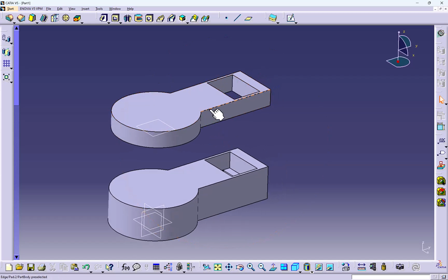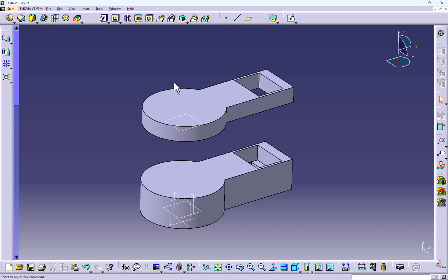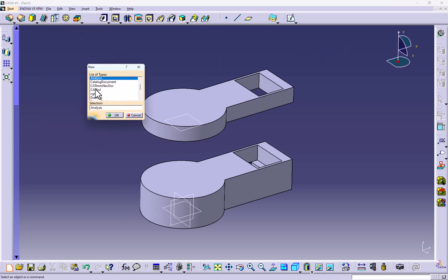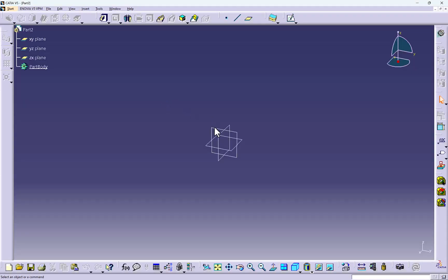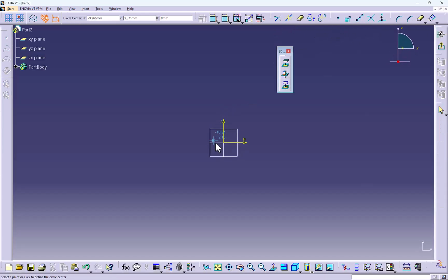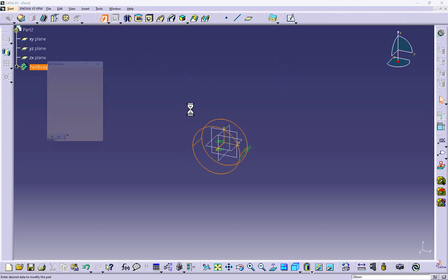Next, we can do one thing here. We have circular body cases. Now this is for the normal case we have seen. We'll see how to use projection for circular body cases. Let me take a new part file here. We'll create a circular object. Let's create a simple object to be understood. Let's make a simple cylinder part, and we'll make a pad here.